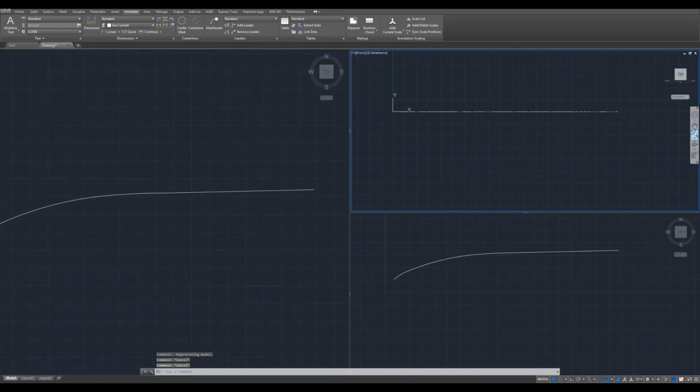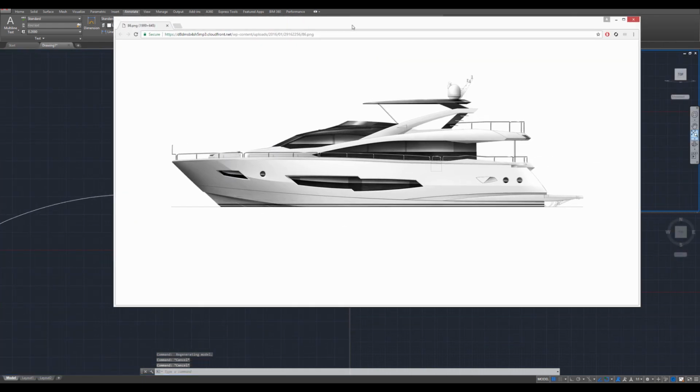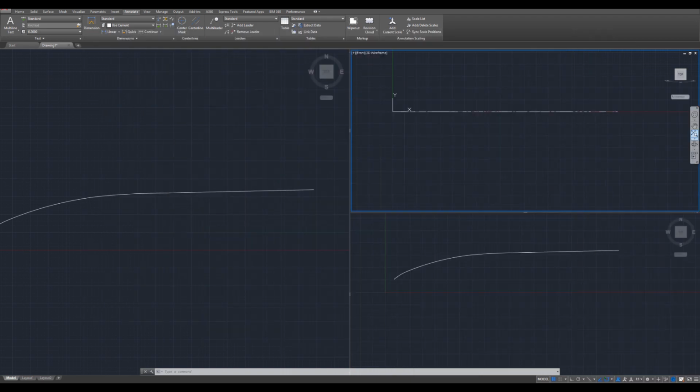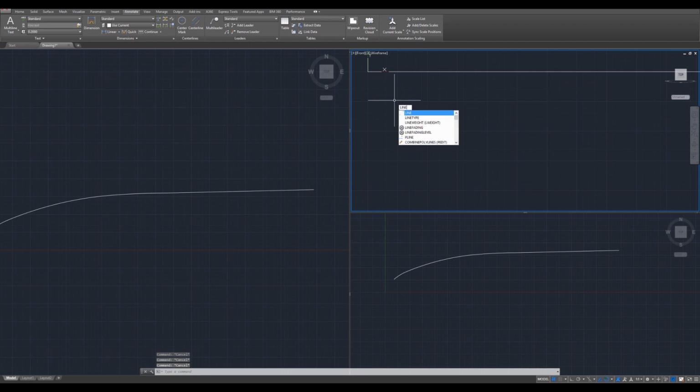Okay, now we need to draw out the front profile. So if you think about the front profile, it's a pretty sharp edge, then a little cut, then a more sharp edge, and then flat. So it's pretty much 4 lines to build that. So that's what we're going to do over here. Let's go to wherever the front is. And I'm just going to take a look at the size and say, okay. And I'm going to draw a polyline, my bad, not a line. PLINE, enter. And I'm going to click at this point.